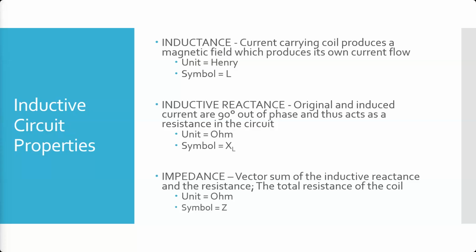So when you bring your probe near a part, it's going to affect both the inductance in the coil itself and the inductive reactance that takes place, and causes a change in those. And so any change in that material is going to change how it's affecting these two items, inductance and inductive reactance. But at any time, the tester is seeing that as a change in impedance.